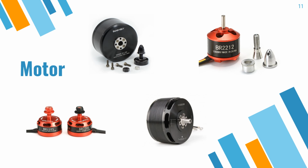There's a direct relation between the kV number and the efficiency of the motor. Namely, the higher the one, the lower the other. So motors with a high kV number are capable of having a high end speed, but are not that efficient, while motors with a lower kV number aren't capable of moving around that fast, but are more efficient, and thus the battery has a longer lifetime and the drone can fly for a longer time.